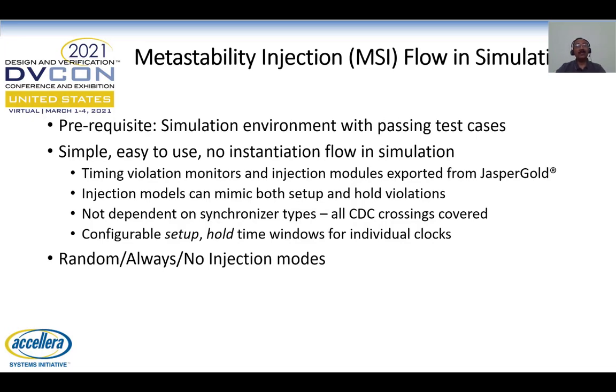All these clocks have configurable setup and hold window, which would allow you to control the rate of injection. But at the same time, different injection modes are anyway supported, random being the default behavior. But for debug, you can always use the other modes like always injection and no injection modes.